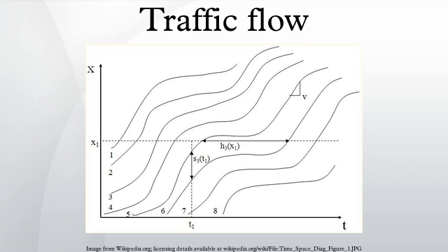The discharge rate μ is the slope of curve NA2, and all the same traffic flow characteristics as in Figure 11 can be determined from this diagram. The maximum delay and maximum queue length can be found at a point M on Figure 13 where the slope of N2 is the same as the slope of NA2. That is when the virtual arrival rate is equal to the discharge/departure rate μ. The N-curve in the bottleneck model may also be used to calculate the benefits in removing the bottleneck, whether in terms of a capacity improvement or removing an incident to the side of the roadway.